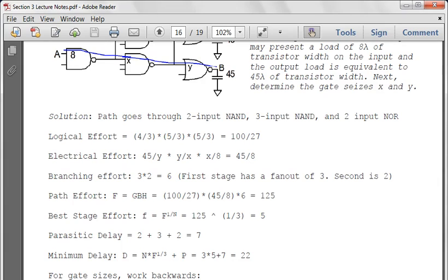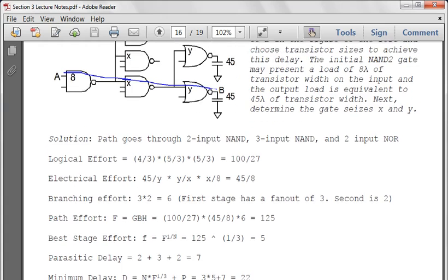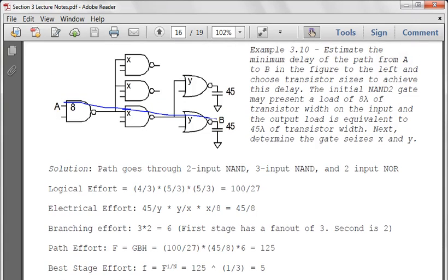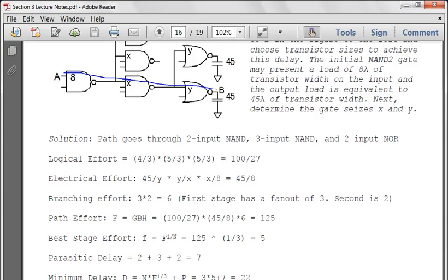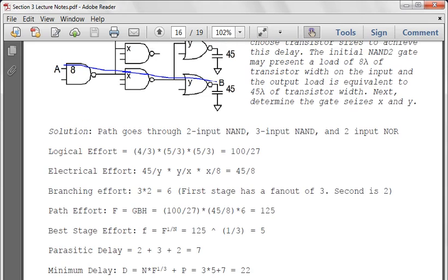So then our final circuit design, using this path, we have all three NAND gates. Use those to calculate our lambda of 10. Both NOR gates should have a lambda of 15. 15 times 5/3 divided by 5 would be 5.